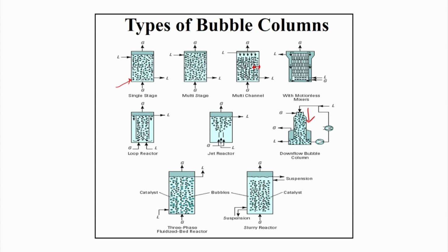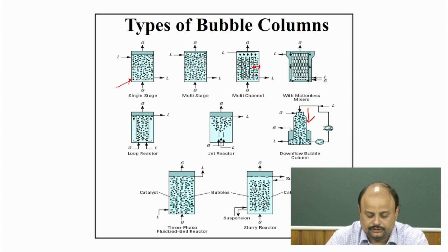If you want better reaction, the mass transfer limitation should not be there. If your bubble size increases, surface area reduces, and mass transfer reduces. That is the typical catch here which we need to understand, and that is why, if you look at the literature, a lot of effort goes into designing new types of bubble columns where the size of the bubble can be maintained.